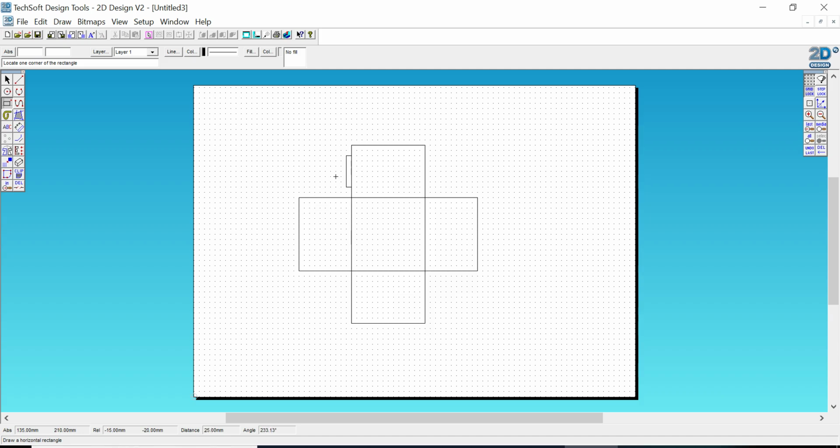It's 2 squares down, so 10 millimeters down, and 10 millimeters up from the bottom. So that one comes out, so the one on the other side has to go in. Make sure the distance is the same. 2 squares, 2 squares. Right, now I'm going to come back to this menu and I'm going to grab my delete button. Hold it down, don't delete any, do trim. So find the trim button and double click there to delete that line. Same on that one to delete that line. Right, we need to have rectangles like that on both sides.